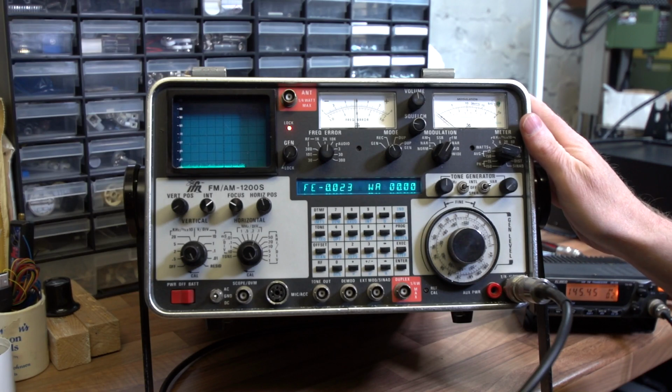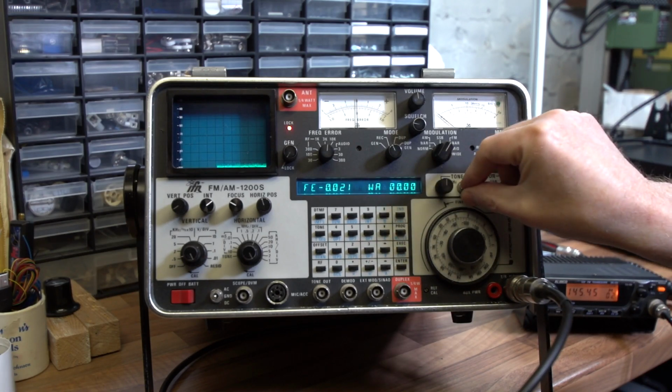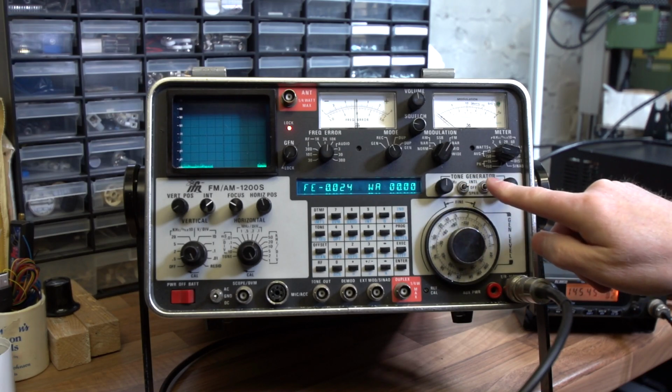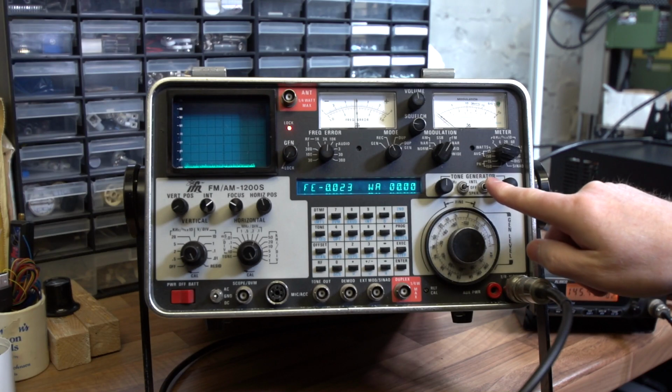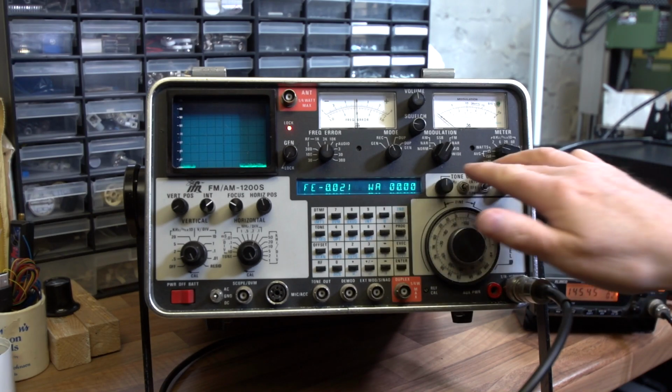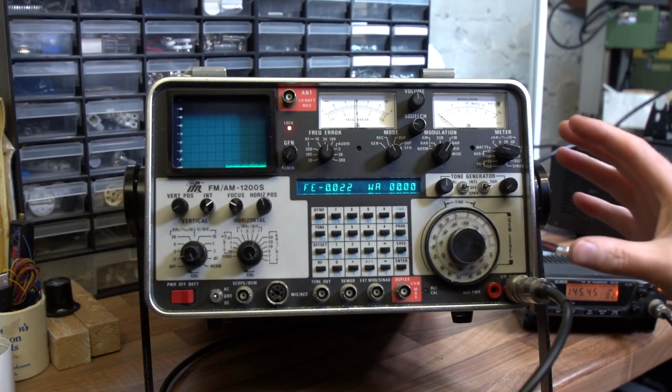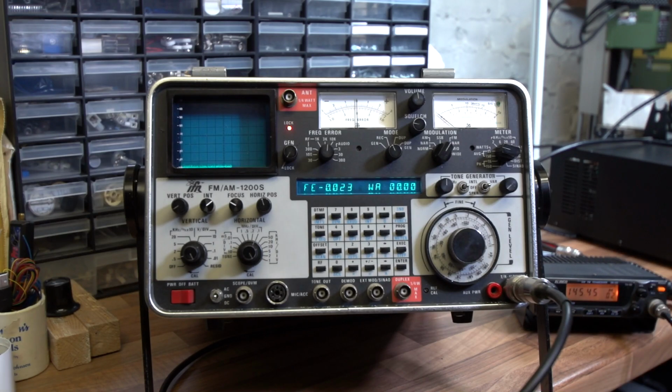It's also got other functionality, like an audio tone generator calibrated at 1 kilohertz, and another audio generator which you can set to any frequency you like within the audio range, which is very useful for dual tone testing. It's also a receiver and a transmitter, so it's a generator as well. It will generate RF at small levels, good enough for checking receivers, to see if the receiver's working correctly, if it's sensitive enough, or whether you actually have a problem. It's also good for calibrating S meters on radios, so you can get the S meter exactly correct to a standard.